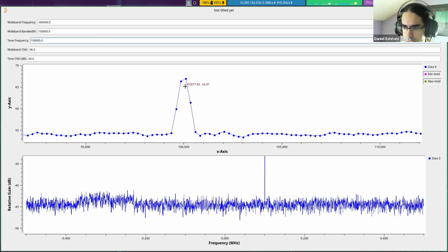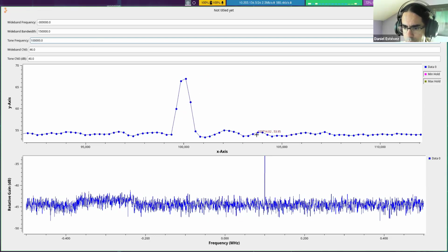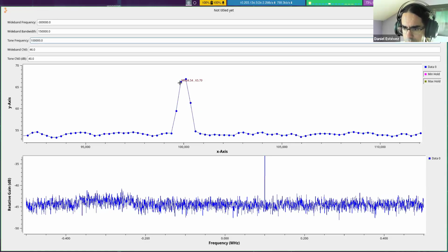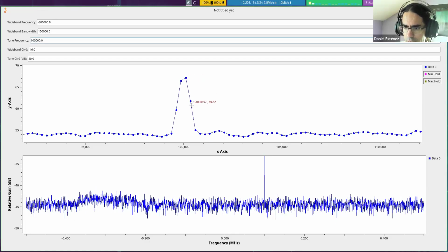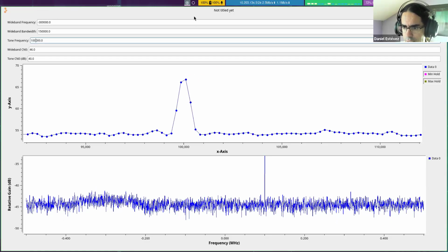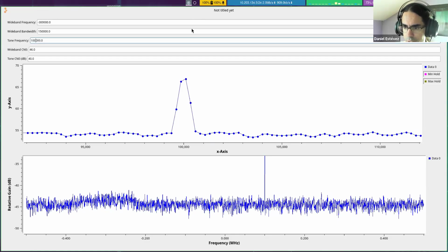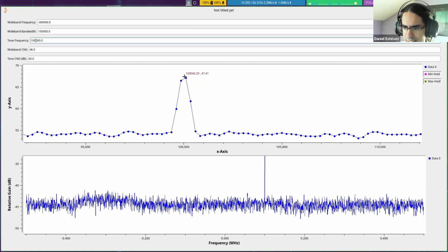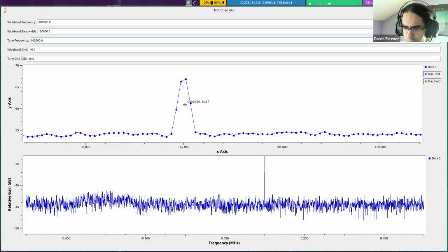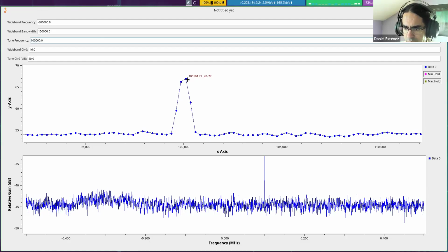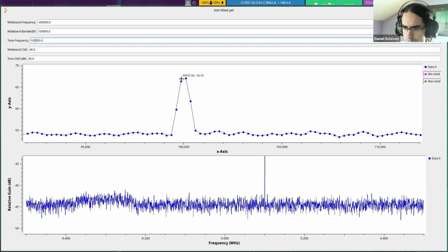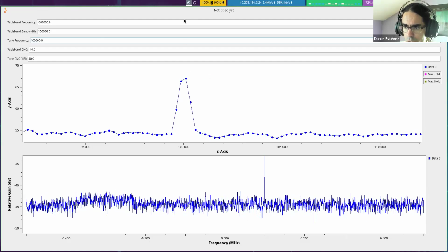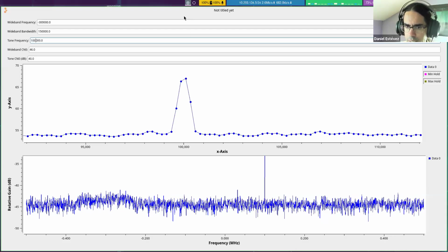And you can see the signal is fairly strong. We can forget about the noise. There's signal power in all these 4 bins. There are a couple of reasons for that. The first reason is that this signal is halfway between 2 of the FFT bins. You can see that by the fact that the power is almost distributed equally between these 2 points.